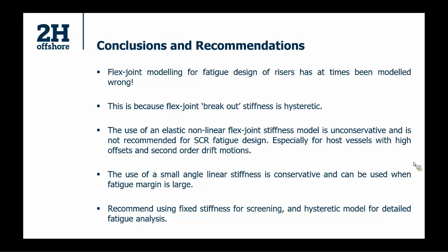The use of small angle linear stiffness is conservative and can be used when fatigue margin is large. Here we recommend using fixed stiffness for screening and the hysteretic model for detailed fatigue analysis.